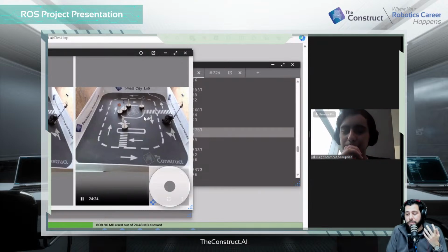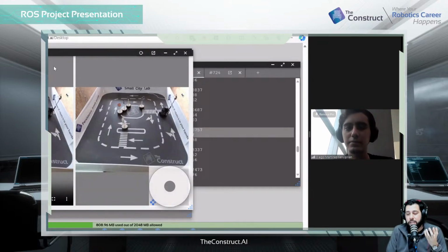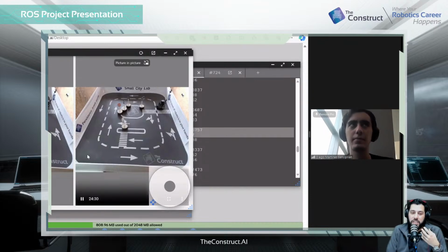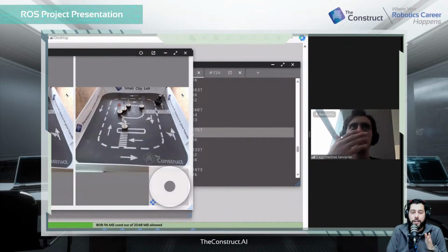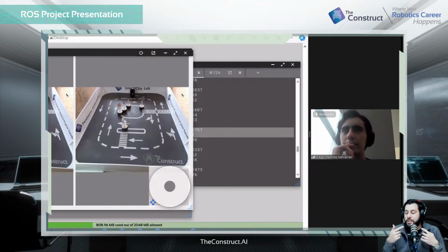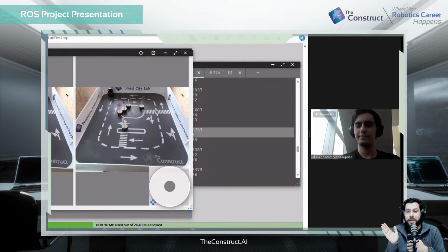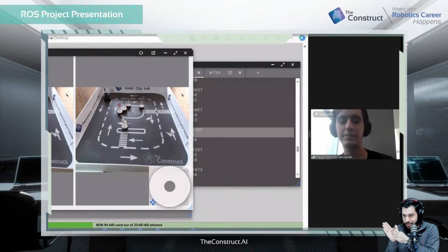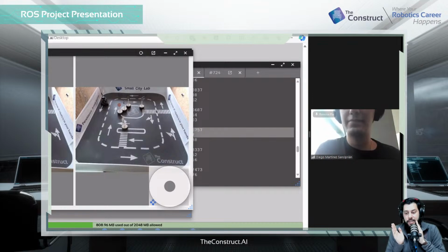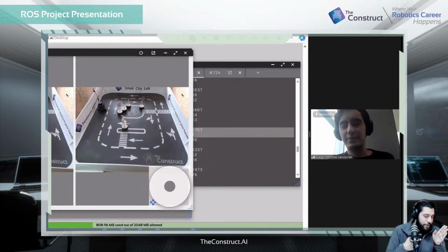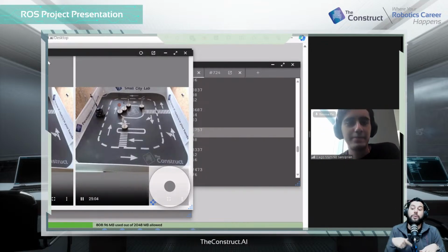When you're looking at the minimum distance, and then you're twisting until the minimum distance is facing the front of the robot, is that one value you're looking at? Yeah, I'm only looking at one value. Okay, so that can be one problem right there, because let's say your node is going either too fast or too slow, the frequency of it, and let's say right before that is accomplished, you're looking at a value that's not the minimum, and then in the next step that your code loops through, it jumps past it. Yeah. So that means it's got to do a whole new lap.